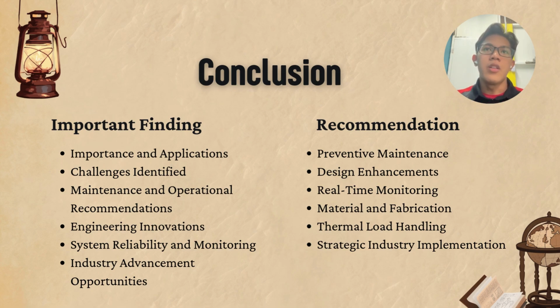For the second one, design and enhancement. Incorporate thin surface and enhanced tube geometries to improve the overall heat transfer coefficient, especially during conditions with unstable fluid properties. These enhancements not only extend equipment lifespan, but also improve energy efficiency and reduce operational expense.